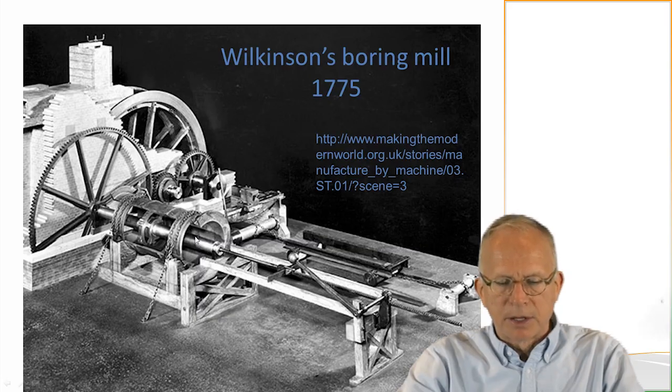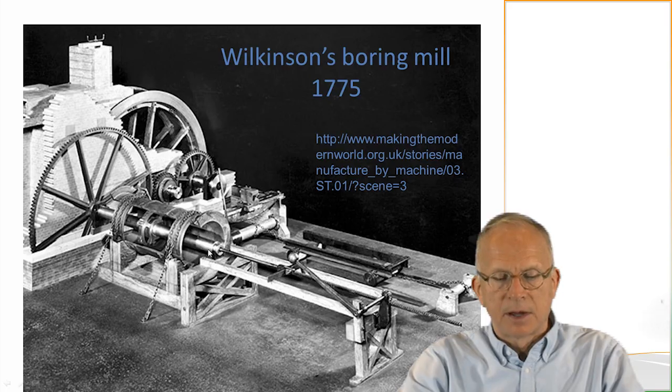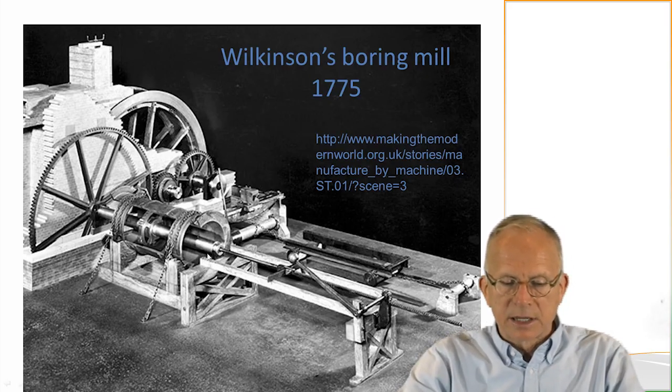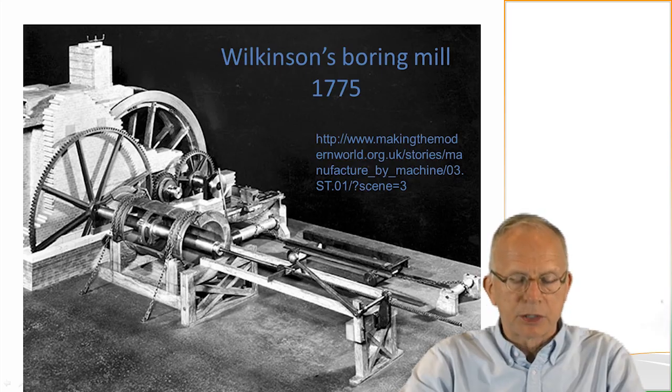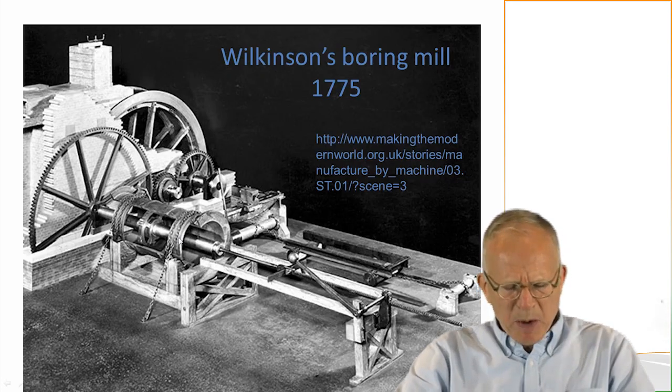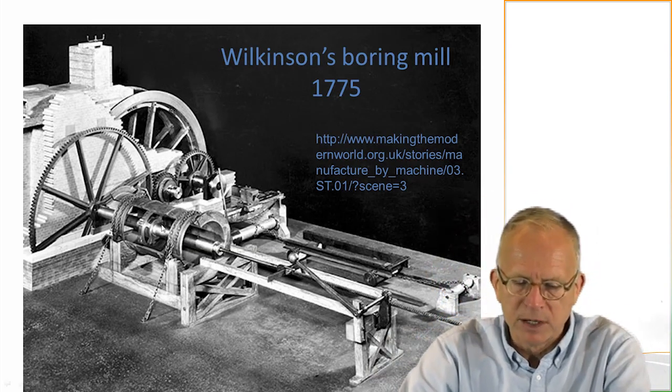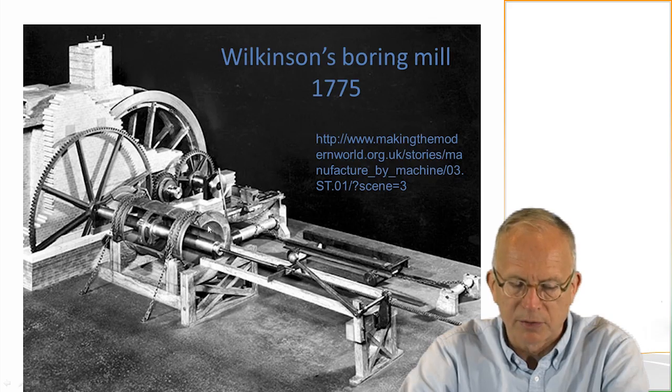Now, previous experience had been boring out cannons, which didn't have the same tolerances. The tricky thing was to get a piston to slide inside a cylinder, but fitting tightly enough in the cylinder so that the steam can build up pressure to do work, but not so tight that it seizes on the cylinder, or there's problems sliding in the cylinder. So there's a very small tolerance band. And in order to hold that, you needed a different kind of process than boring out the cannon.